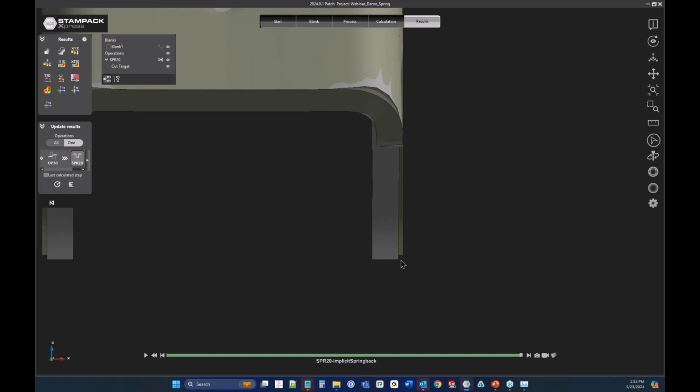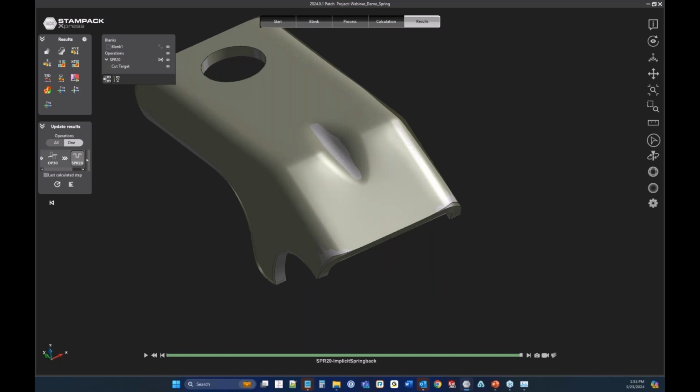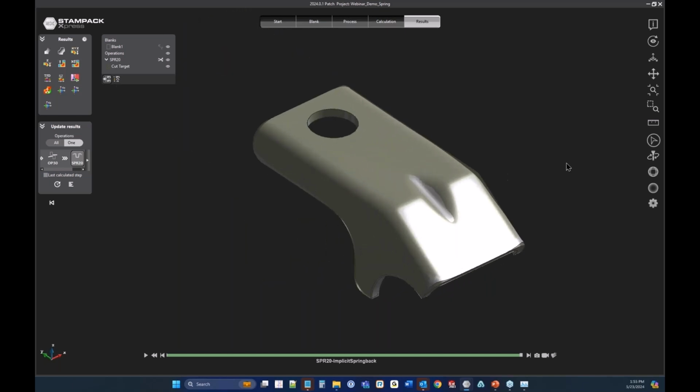The way those rocker forms were developed was through multiple different iterations of me running this software, in order to know exactly where I need to position those rocker forms, how far they need to come down, and how far they need to push in. So rather than trying this many different times in the press, you can simulate it once, know the geometry you have to do, and work with exactly that. All right, and that is everything I have for the full development of this die here.